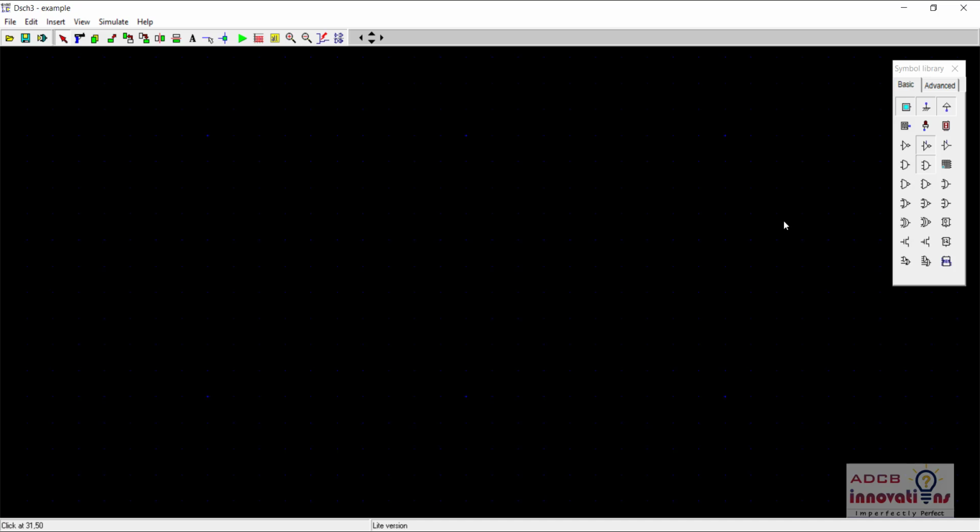So now let us make a very basic design, that is the inverter. All right. So we know the schematic of an inverter. Those who know it, great. Otherwise, I will tell you, don't worry. For an inverter using MOSFET, you connect a PMOS and an NMOS in series, and then you need to connect the input and output and voltage and ground.